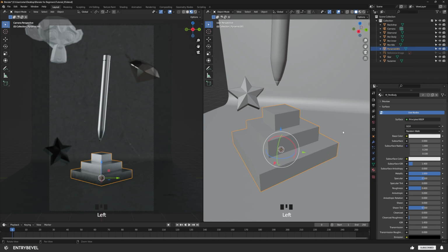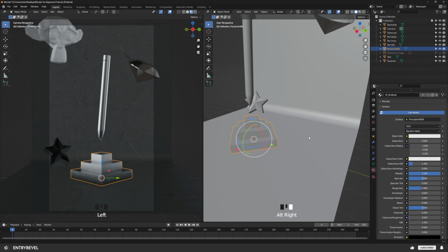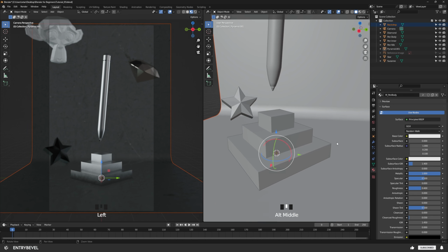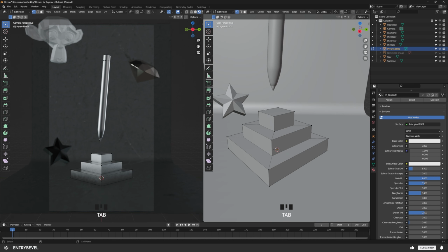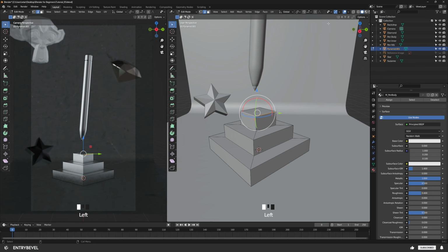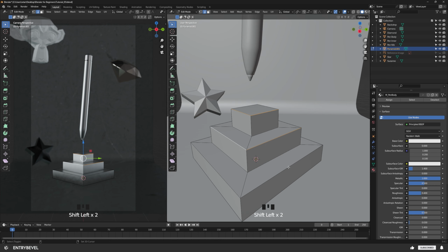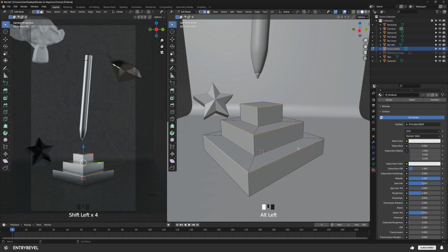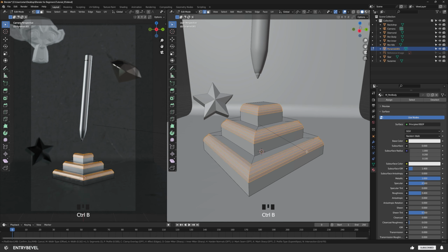So we have to add bevels. Like we added bevels to this backdrop, you can add that to edges as well. So to do that, go into edit mode, make sure you're in edge selection, which is 2, as you can see right here. Select these. This gizmo is a little distracting. So I am going to turn them off. Select all of these. Now press Ctrl B to bevel. And let's reduce the number of bevels like so and make it really tight over here.